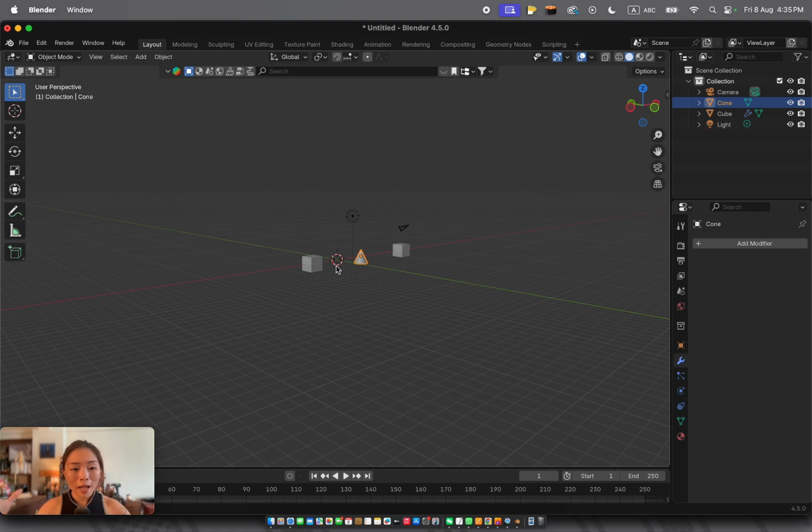For example, if I'm having a symmetrical room, this is perfectly symmetrical, and then I'm putting two rows of chairs or benches in the center of the room. I want them to be a little bit further apart. Then I will create one set of benches, and then I use the mirror modifier and select the room as my reference. And then if I select the room as my reference, I'm having that as the center point, and then I can clone another set of the benches on the left hand side. So this is how I can use modifier to help me reduce the working time to do the complete model of an interior environment.